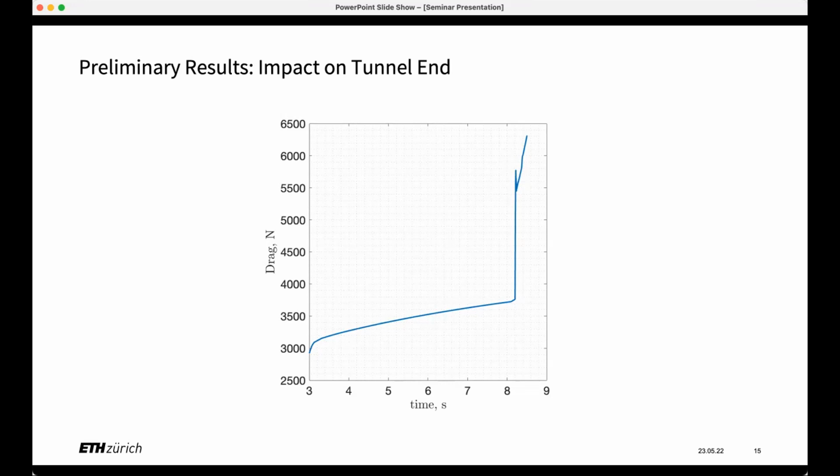So you have a further increase in drag, but more importantly, a really sudden increase in drag that the passengers would definitely feel, and that the pod's induction motors wouldn't be able to counter. So you would all of a sudden get quite a significant deceleration, which is why the patterns that we're looking at at the end of the tunnel are quite significant, because if you get this in cruise, then all of a sudden you will have lost quite a lot of speed.